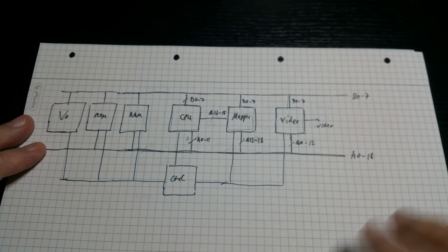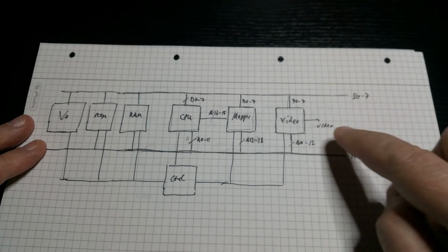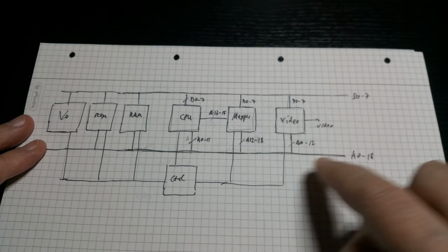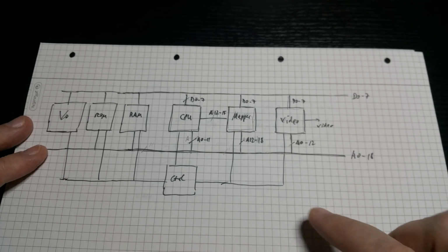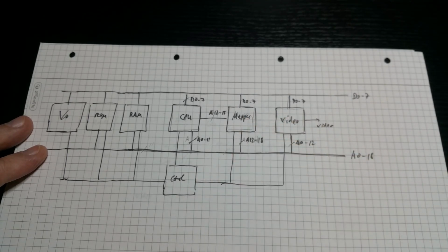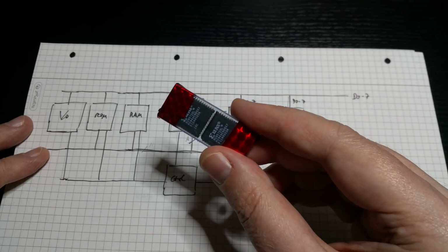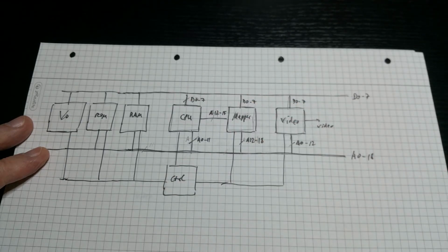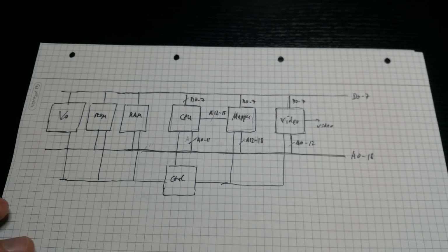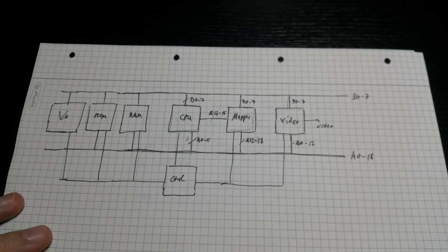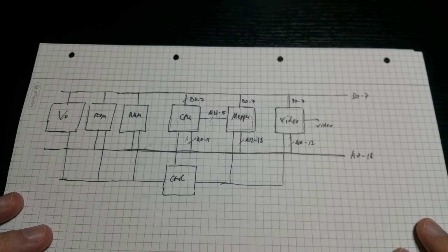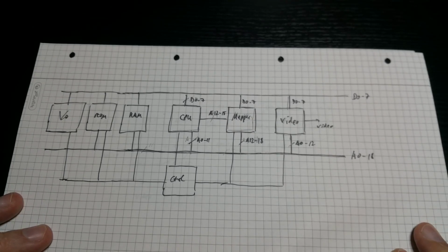Even I was looking into putting the video shift register outside of the CPLD and so on, but that was all adding to the chip count and to the surface area on the board, and also those parts are already discontinued, so you can still get them, but CPLD sockets are basically not supported anymore by the producer of those chips.